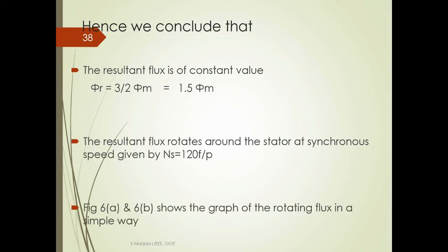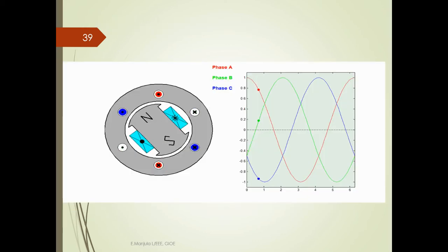So the resultant flux rotates around the stator at a synchronous speed given by Ns is equal to 120 f by p. So here, this is an animated part.